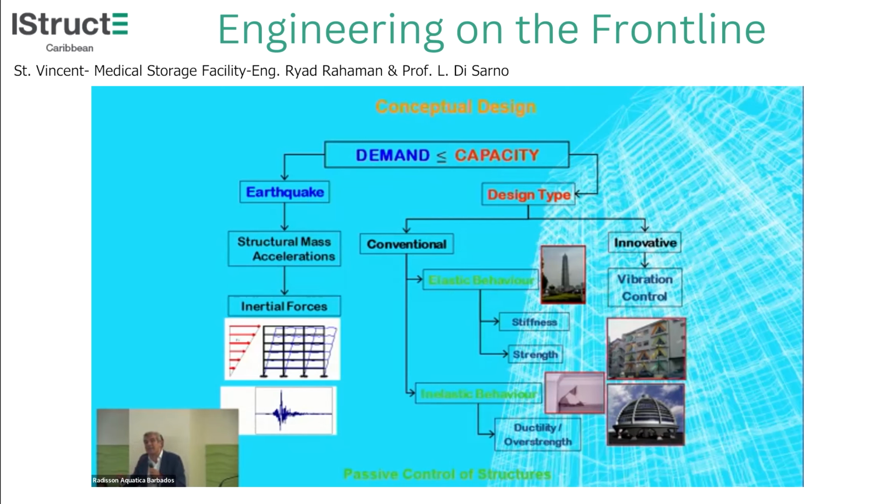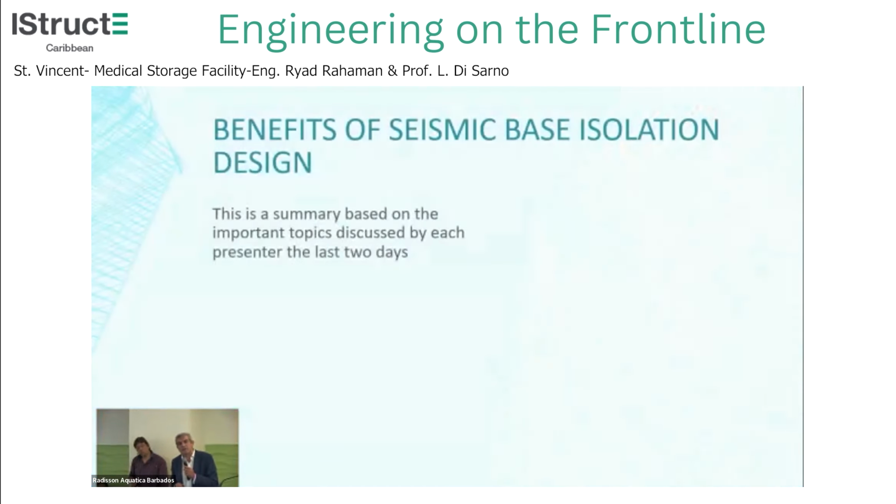This is an application of a retrofit of a building in Italy for a school. This is the civil protection, near Rome, and it was built on a number of isolators. Why? Because these are critical facilities that one wants to preserve so that they will be operational, like hospitals, soon after a major event. Go to the next one, which I think is the last.